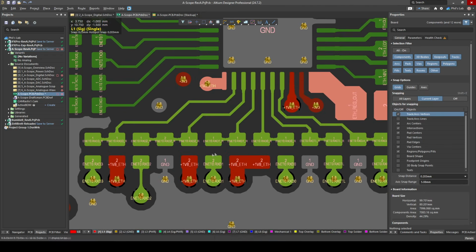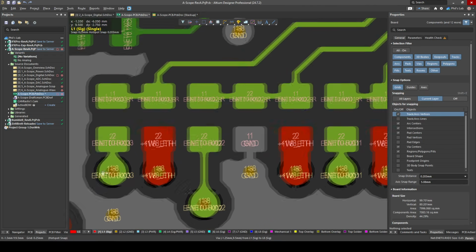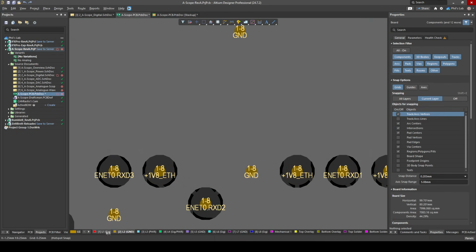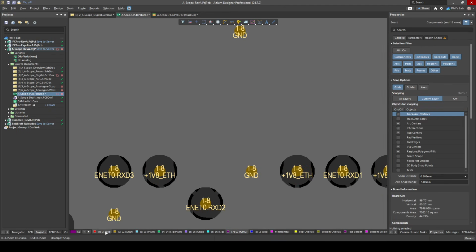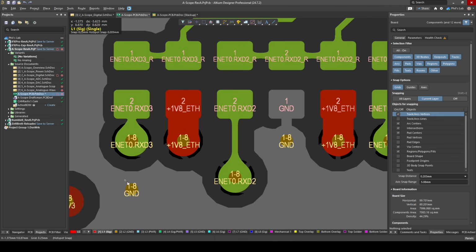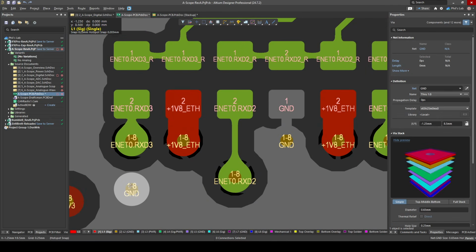Also, anytime I do a layer transition, for example, from layer 1, which has a reference at layer 2, to, for example, layer 6, which has reference layer 5 and reference layer 7, I try to place transfer vias. So a grounded via that aids in the Z-axis transition when I'm switching reference planes. So this stitching via also serves as a transfer via for RXD3.